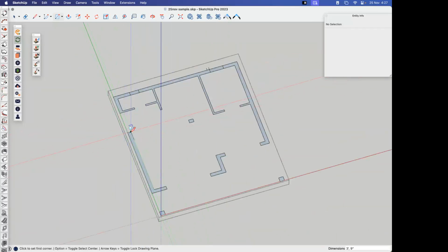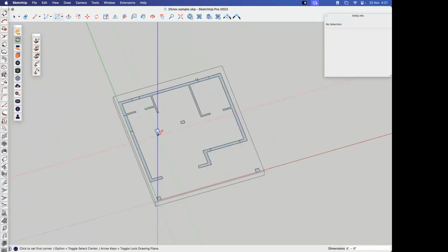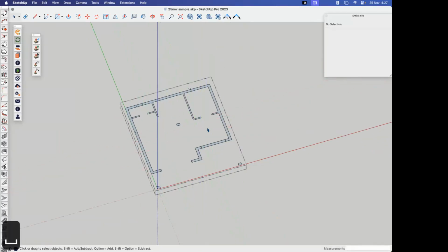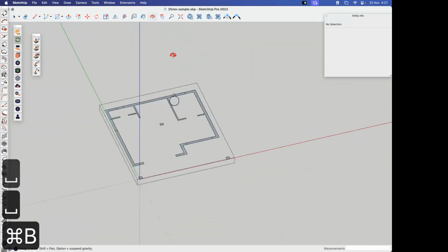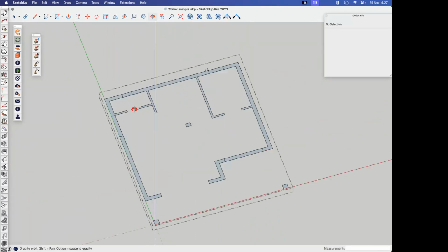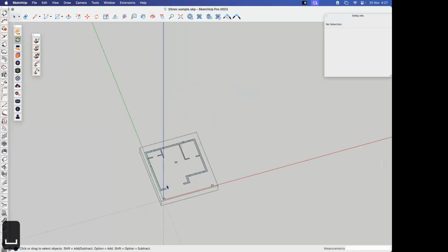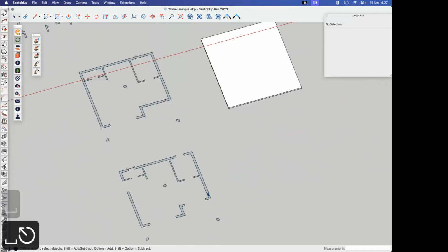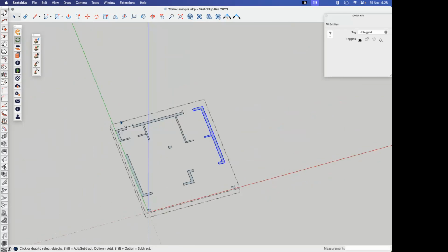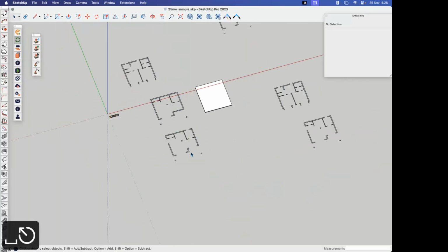So we have a window here, we have a window here. Let's say we have a window here. So technically you have to imagine cutting a section at 2 feet of the plan. So basically we get the entire plan which is there with only the door opening. So we have one door opening here, one door opening here, and one door opening here. Then later we should imagine a plan where we have all the openings, which is door and windows. So which is our existing plan, where we have the door and windows open at once.